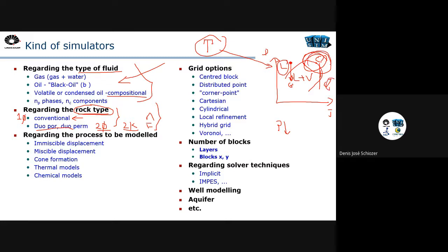When we get close to these critical points, the fluid is not really a liquid or really a gas. It is a fluid that has properties that are something in between. So the behavior is very complex, and when we are in these conditions, we have to have a special thermodynamics treatment, okay? That's when we call supercritical conditions, and we are above the critical point, okay?